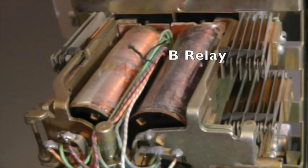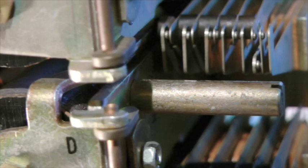The operated B relay grounds the sleeve lead back to the line finder. This provides the holding ground that maintains the line finder switch in its connected state. When dialing begins, continuity of this holding sleeve ground is maintained by succeeding switches in the dial train. Back in the line finder, the operated F relay closes the operating path for the D relay via its primary winding.